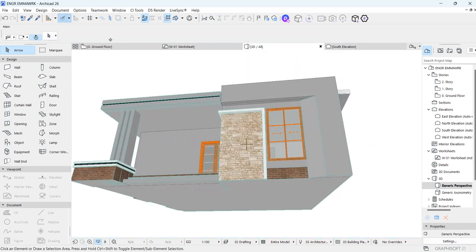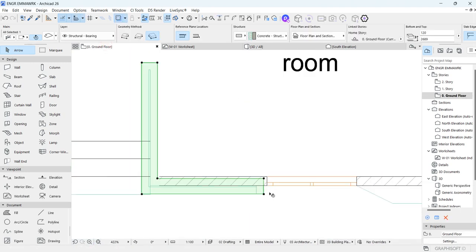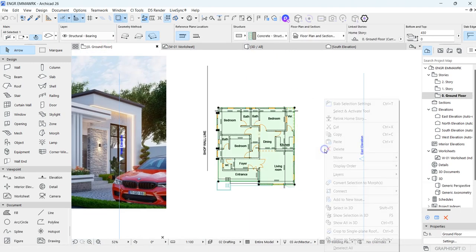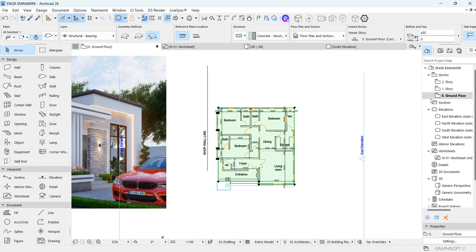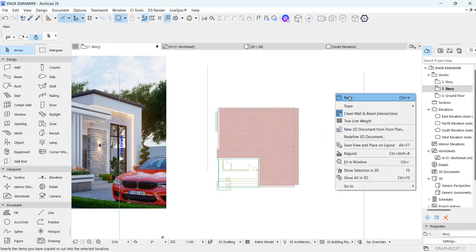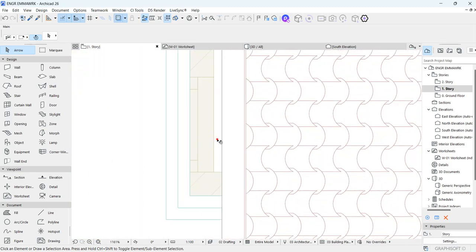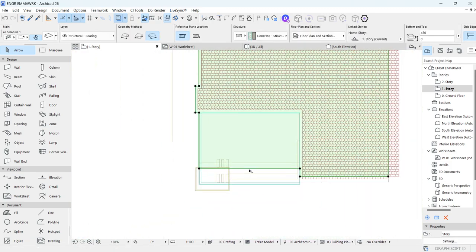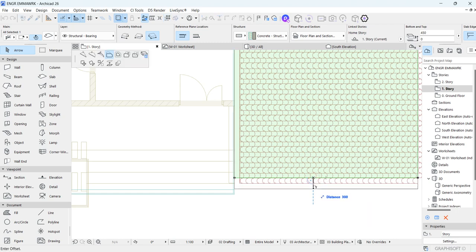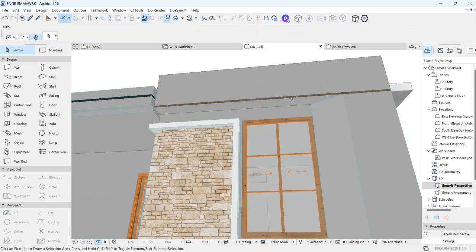We have to put a ceiling, which I will copy and bring to the first floor. I will take it from this place and extend this out, so it will be a thickness of 50, and I will raise it up by 50, so it acts as our ceiling.